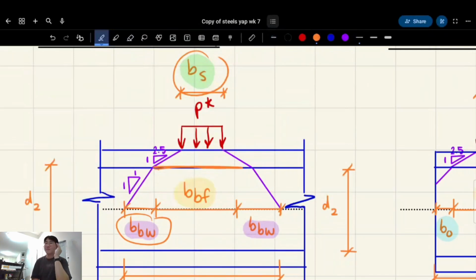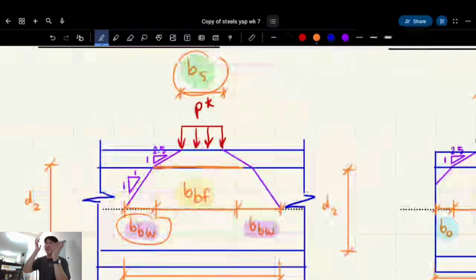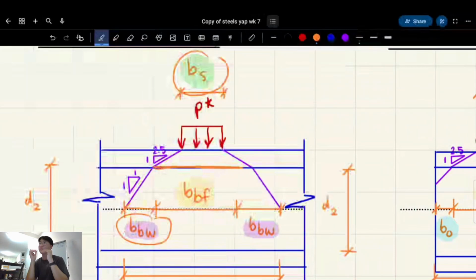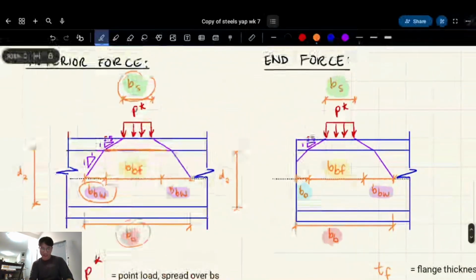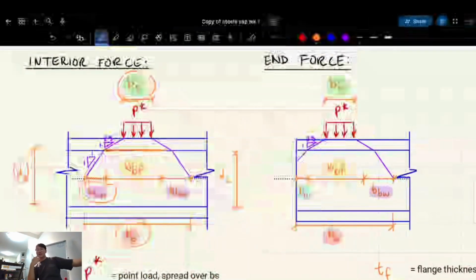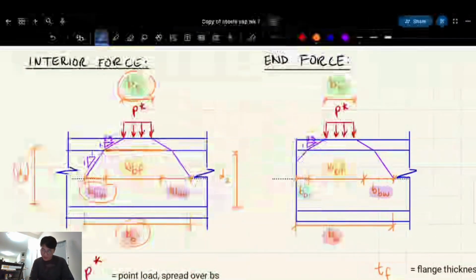Now we said about shear that the max shear happens in the middle of the web, right? So that's kind of what we care about in the end. It's BB, the bearing width that's been transferred and increased until the middle of the web. That's everything, right? D2 is slightly different to D1. So you remember how in the previous part we talked about D1 as the clear depth between the flanges? D2 has a weird definition, but it's essentially the same thing.